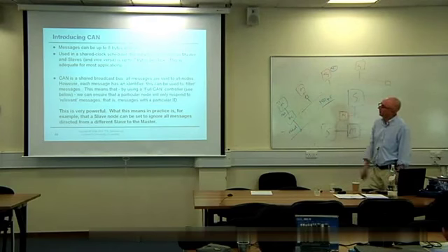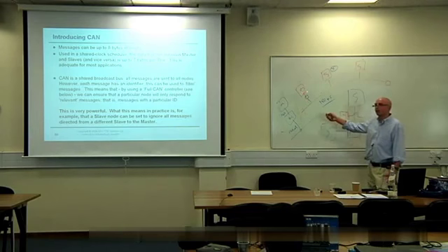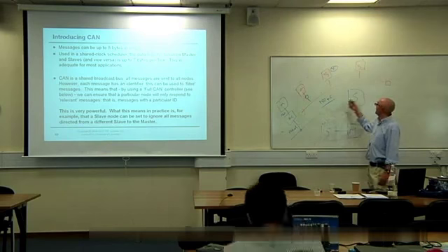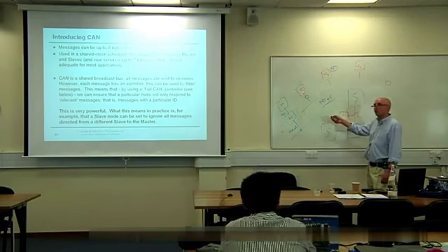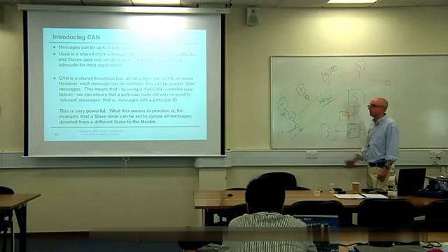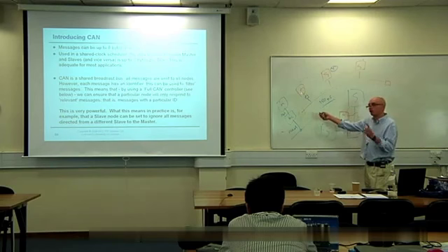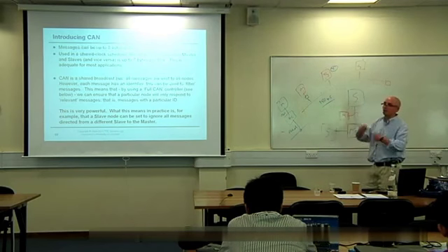What's neat about this, the fundamental thing that's neat about it, is this guy is going to send tick messages. And we want those tick messages to generate interrupts on here. Do we want the tick messages to generate interrupts here on the master node? One interrupt per microcontroller. That guy's got his scheduler triggered by timer overflows. And he knows when the messages will arrive. So he can poll the messages generally.